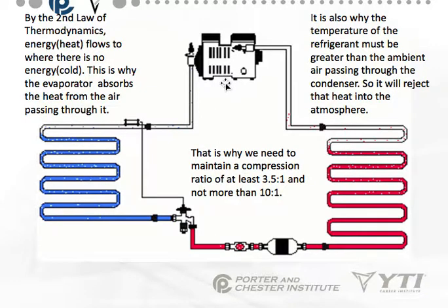We need to maintain a compression ratio of at least 3.5 to 1 and not more than 10 to 1. Again, this is not something you need to measure. This is something you're going to see on the specs for your compressors and your entire systems. But 3.5 to 1 and not more than 10 to 1 probably comes up on some of the certification and licensing exams.